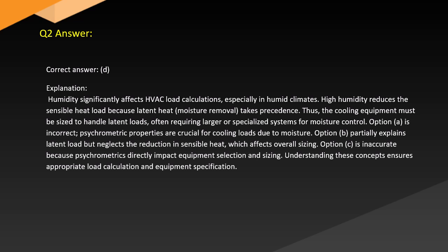Answer. Correct answer. D. Explanation. Humidity significantly affects HVAC load calculations, especially in humid climates. High humidity reduces the sensible heat load because latent heat moisture removal takes precedence. Thus, the cooling equipment must be sized to handle latent loads, often requiring larger or specialized systems for moisture control.